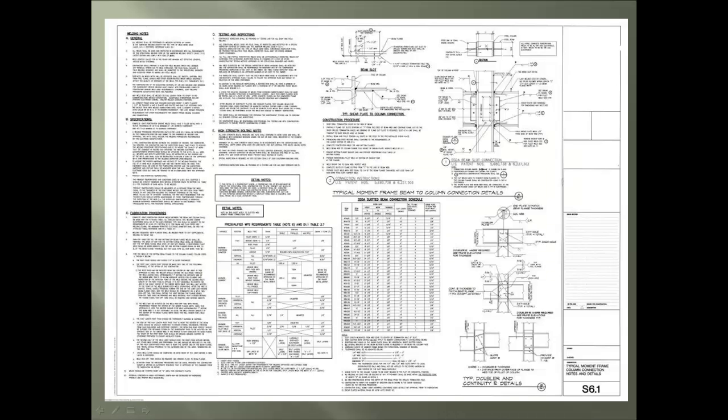We now will look at the testing and inspection requirements. Here are some items for both the QC and QA professionals. Shop and field welding shall have continuous inspection. Special inspection shall be approved by OSHPD. Field welds shall be made in accordance with the approved contractor's plan.